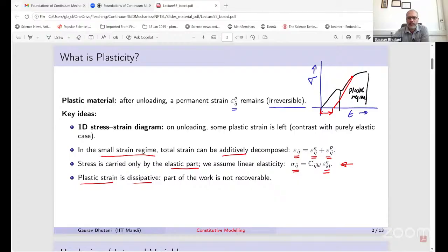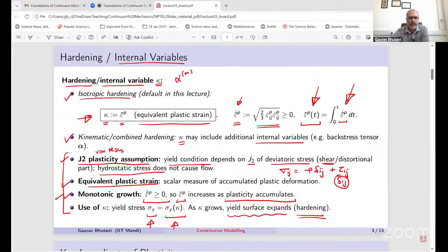If you take a ductile wire and you bend it, what you see is that after bending, you leave the wire. It comes back slightly, but mostly it stays bent. So that staying bent is the plastic deformation. And then it comes back slightly, so that's the elastic strain. It's the elastic part which helps us relate the cause and the response. But it's the plastic part which is the internal variable that we require for these kinds of situations, which in